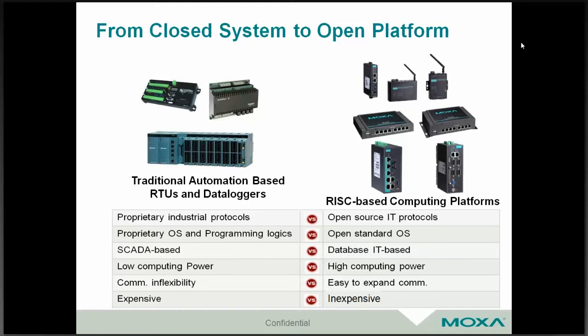First, the PLC, RTU, and data logger normally come with proprietary industrial protocols like Modbus, though Modbus is not considered proprietary anyway, Profinet, EtherNet/IP, sometimes DF1, very special protocols. Whereas if you compare that with RISC-based computing platforms, open-source IT protocols are always available, for example SNMP, the Simple Network Management Protocol, things like that.